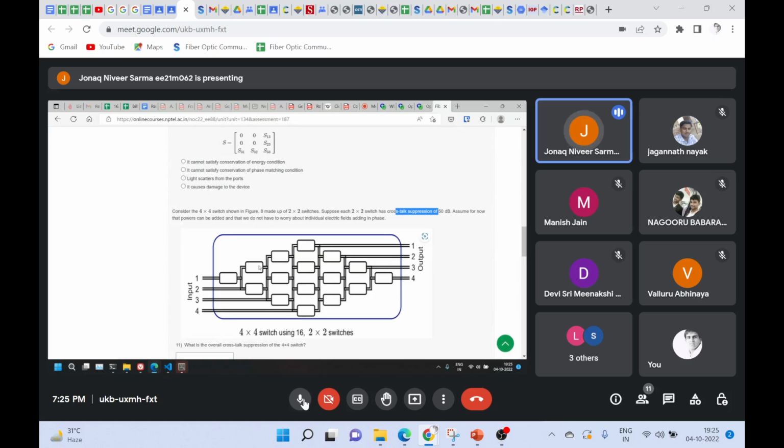Near 0 dBm went here, and again here an unwanted minus 50 dBm will come to the other port. So minus 50 dBm contributed from here, minus 50 dBm contributed from here. Both of them adding up will be about minus 47 dBm. That is how you proceed.